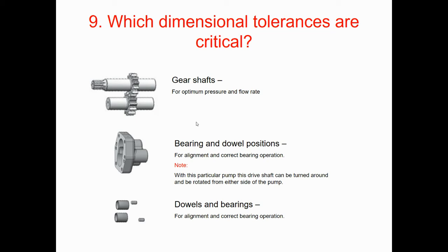So when you try to make gears in the design process, usually you try to reduce the contact area between the gear teeth on both sides, the driven gear and the drive gear. That's simply because we don't want to have more losses due to the friction between the gear teeth. So reducing this area is going to be the optimal thing, but once again, it's going to cause losses in the force transformation between the two gears.